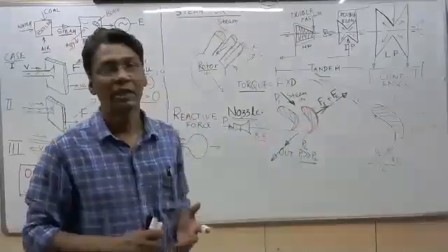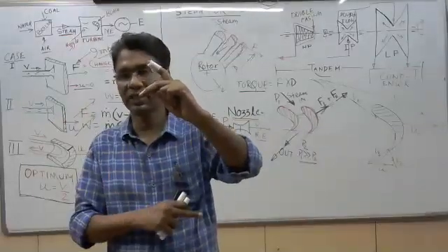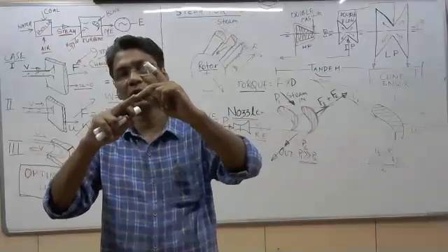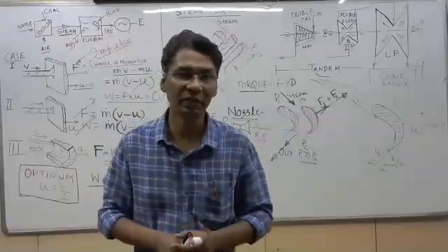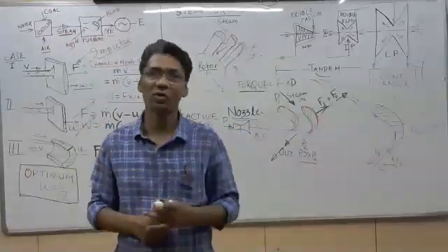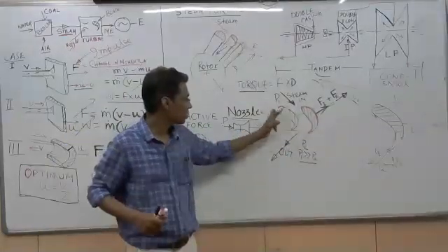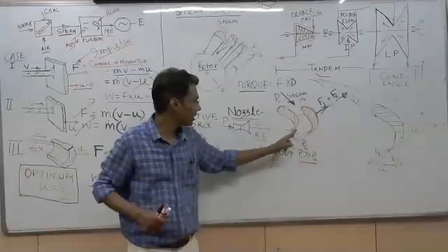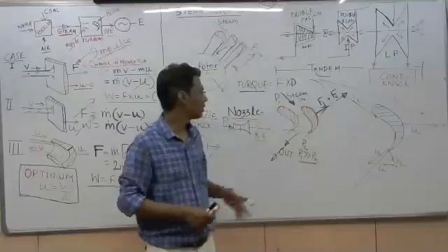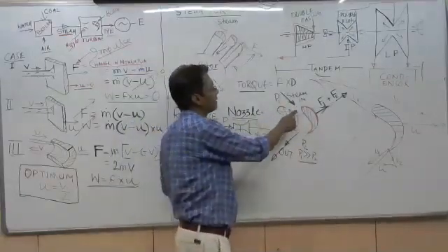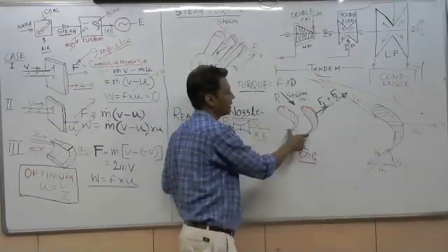Similarly, steam input is there. If the steam output velocity can be increased much more than the input velocity, then we will get some reactive force, and that can be done by a pressure drop across the blade. That means we will design the blade in such a way. Suppose this is the blade cross section. This is one blade and another blade is placed side by side around the periphery. We are considering two blades. You see, the passage here is this one. Entry is there. That is the throat area, and that is the output area.